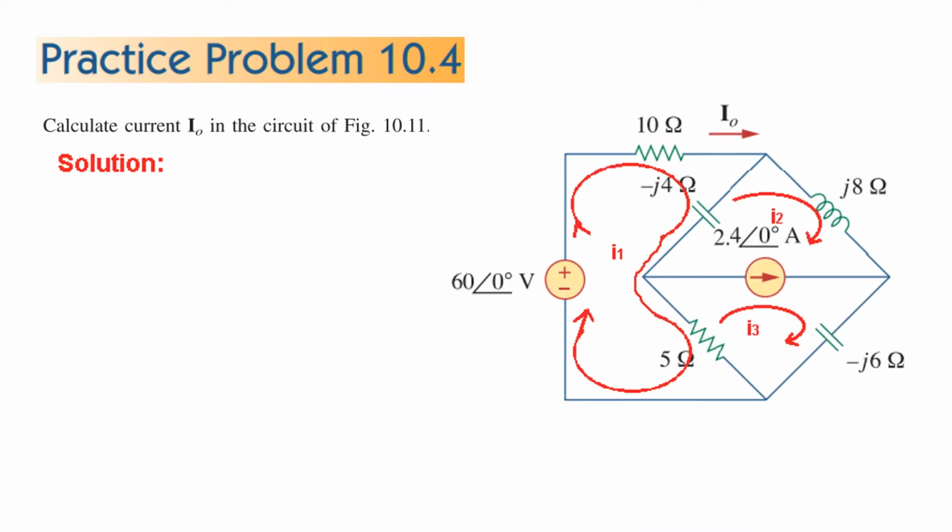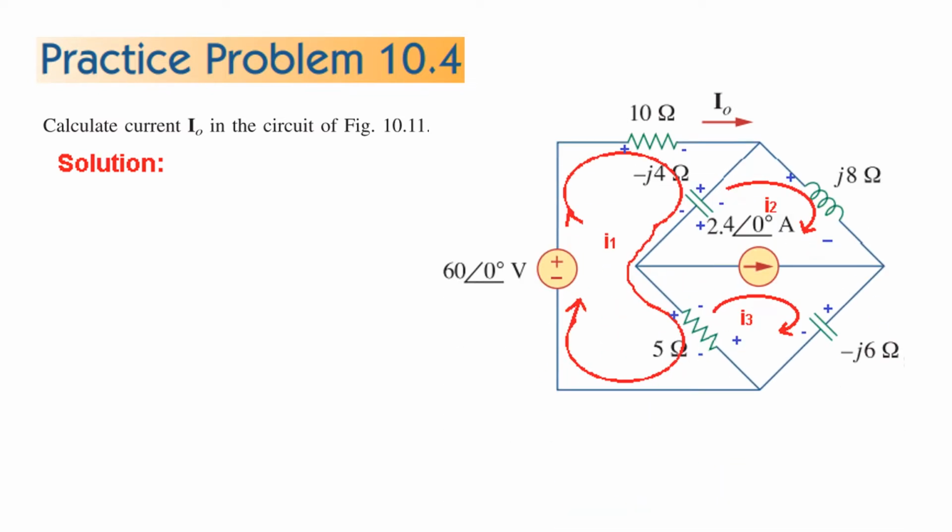First of all, we mark all the currents and we name them. So this is I1, I2 and I3. And then also it is a good practice to mark the voltage polarity. And we know wherever the current touches that point becomes positive. So positive, positive, positive for this one. Similarly for this is positive, negative, here it is touching positive, negative. So you mark all the polarities.